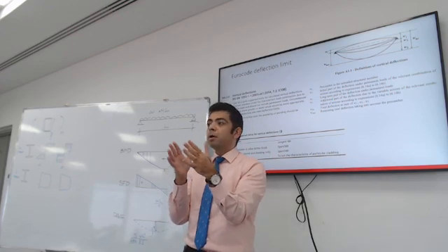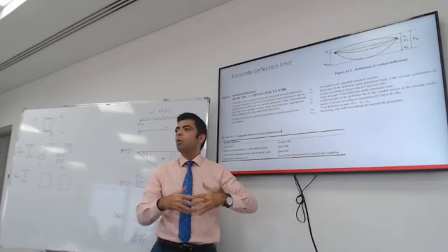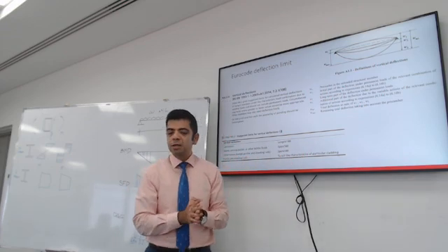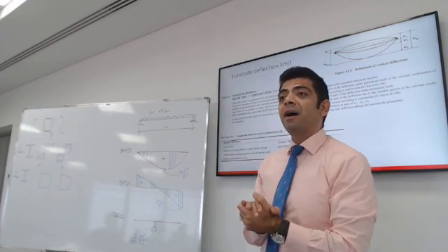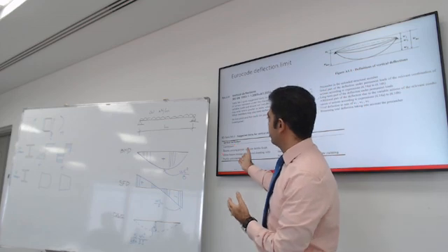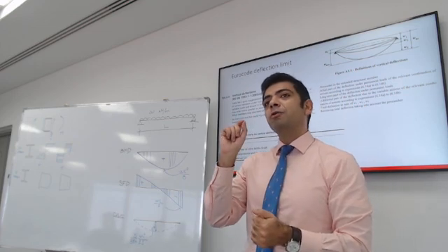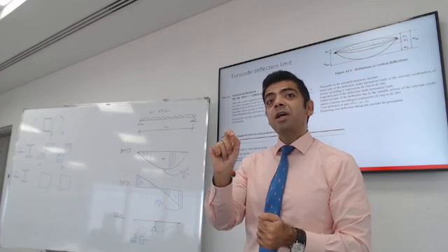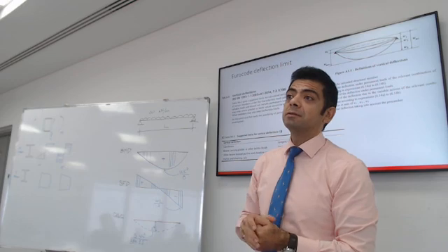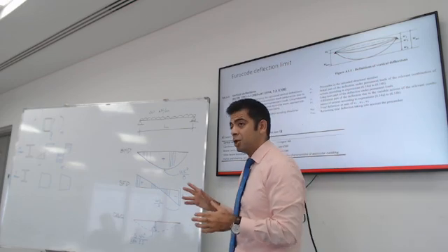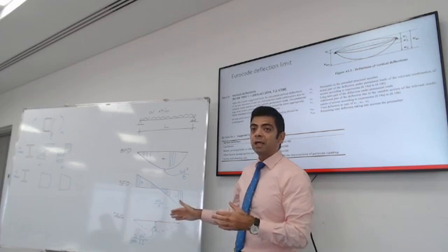Each member of the European Union can have some say or control over what the allowable deflection is. So here is what I want you to know about the suggestion for the UK version. The Eurocode for the UK suggests that you limit the live load deflection only. It does not ask us to check or limit the deflection due to dead load.